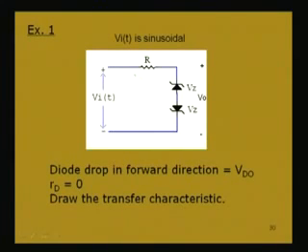So, if you give a sinusoidal voltage, you can find what the output will be. Whenever the input voltage is in the positive half cycle, this Zener diode will be reverse biased, but the other diode will act like a normal diode when this point is positive with respect to this point. But when the voltage across these 2 points is greater than the total voltage drop, that voltage drop is Vz plus Vd naught.